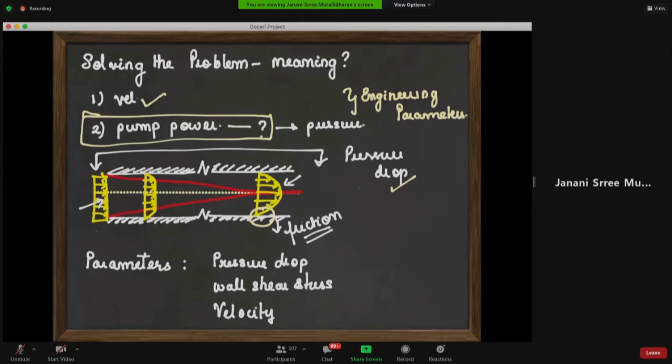You're going to lose energy to friction. So there is a pressure drop. Now, if flow has to happen, then the pump has to be able to cause a thrust to overcome this. Okay. So the entire process, as you can see, a large part of the contribution is this interaction with the wall. Okay. And a related term with the friction is your wall shear stress.